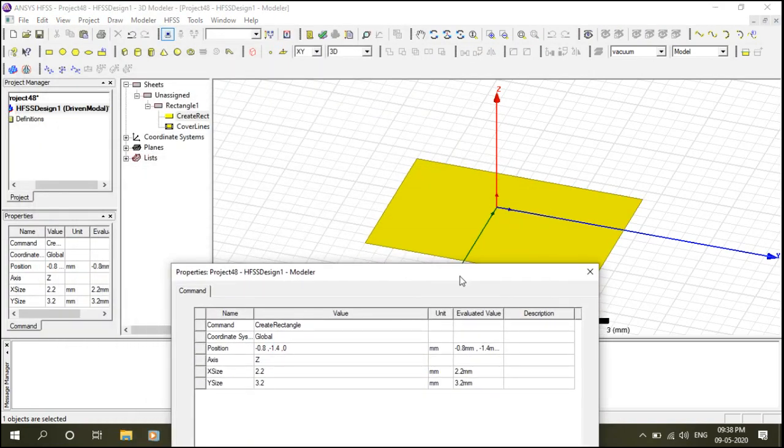So to set the coordinates and dimensions, first of all you have to define a particular vertex of this patch. So I am choosing this vertex. So what will be the coordinates of this vertex, and I will make this antenna symmetric about the coordinate axis. So the coordinates of this vertex will be, the length of the patch is 13.19, so this should be minus 13.19 by 2, and the y coordinate will be minus 17.54 divided by 2,